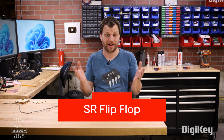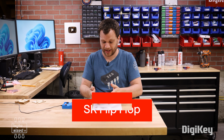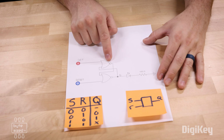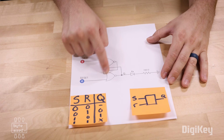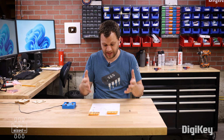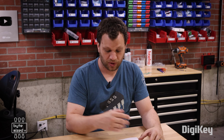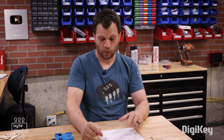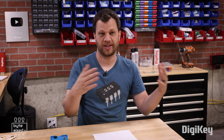What happens when we combine 2 logic gates into a circuit like this? I've got 2 NOR gates and they are cross-coupled, which means the output of one is fed into the input of the other. And so when we combine logic gates like this, we get something interesting. We still have 2 inputs. We have a set and a reset and 1 output, which I have tied to an LED. When both of the inputs are inactive, they're both 0, our output just stays the same. Whatever it was before, it will remain the same.